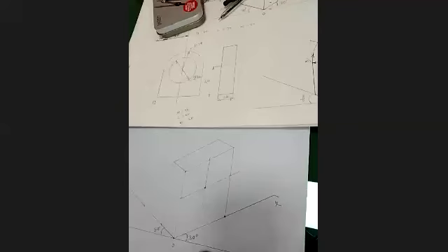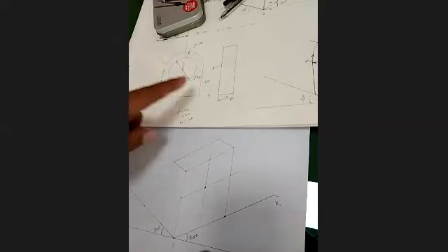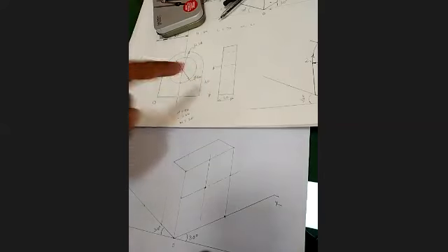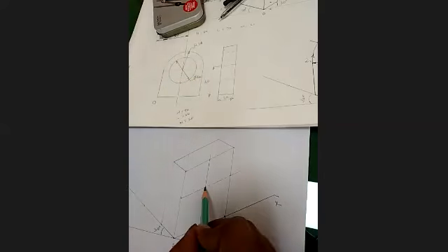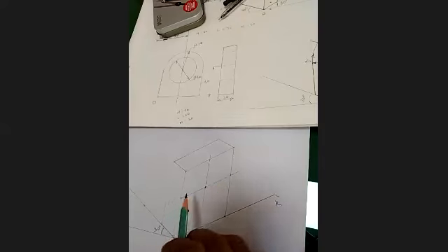Yes, sir. Okay. Now, what is the diameter of the circle? Say complete circle 360. It's a 40. Means radius is 20, right? So from center point on each axis, on each direction, all four directions, you have to take the 20 millimeter distance in compass.